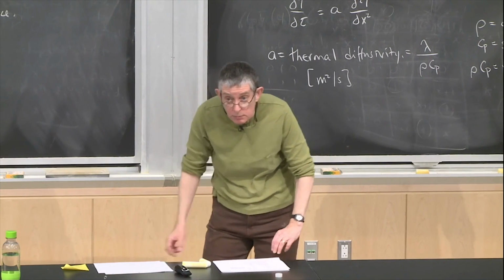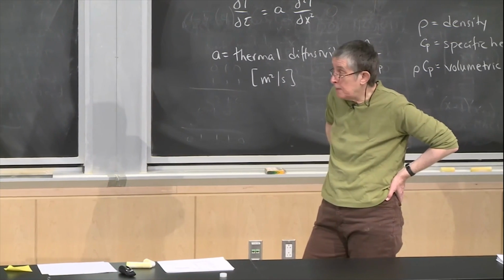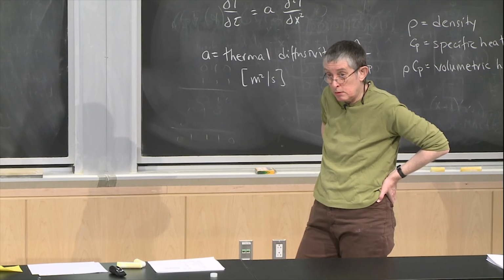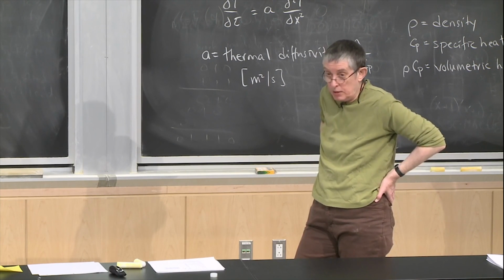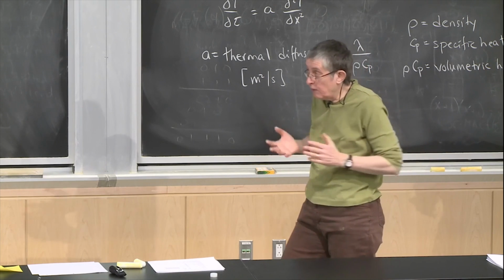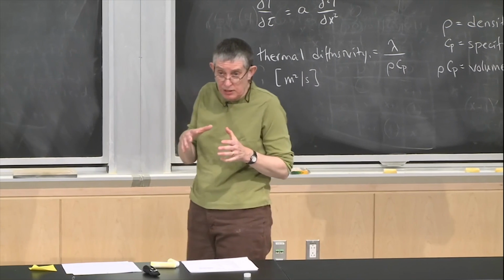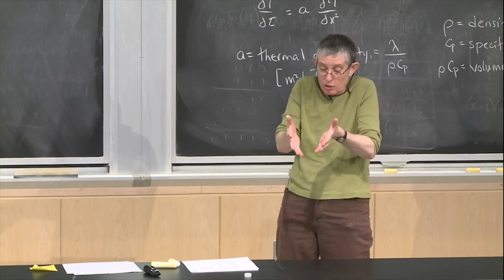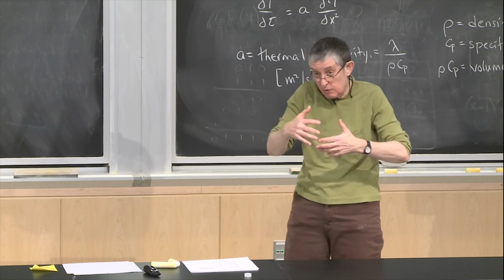All right? Yes? So you can only have those lower thermal conductivity foams if they are closed cell with a different gas, right? Because if they're open cell, it would just always be air. Right, and in fact, one of the difficulties with using the lower conductivity gases is there's a phenomenon called aging, that if you've got your gas inside your foam, it's going to diffuse out into the air, and air is going to diffuse in.